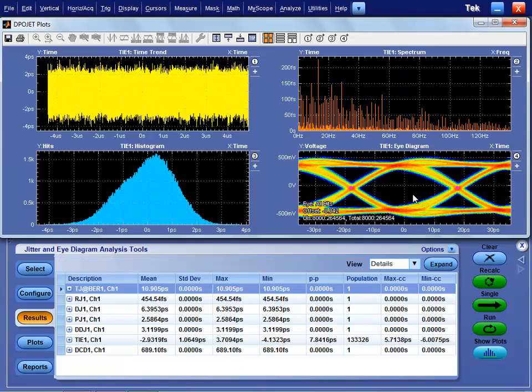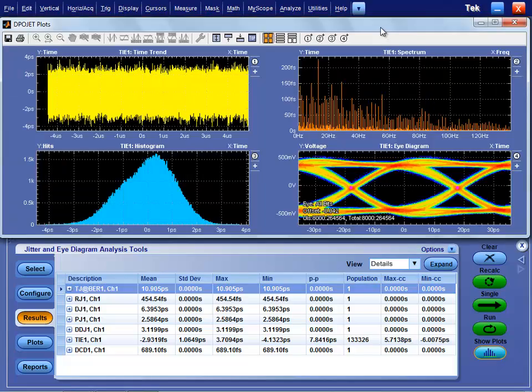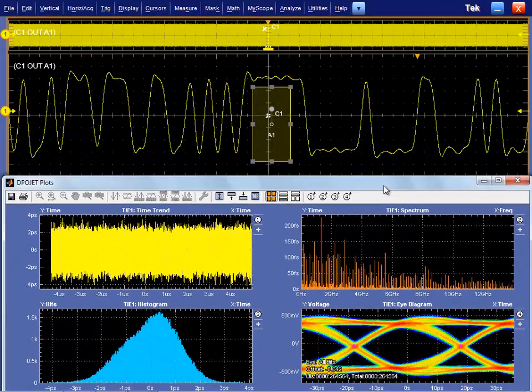So now I have an eye diagram of this signal. If my clock recovery was not set appropriately, this eye diagram may walk around and not stay open. That tells you that, hey, your clock recovery is not tracking whatever frequencies are causing your edges to be non-ideal. So ideally, when you're looking at any high-speed serial, you want to see a long capture. You want to see the bits because you need to see what these bit shapes look like and see if they have decent signal integrity. And you also want to see this eye diagram.